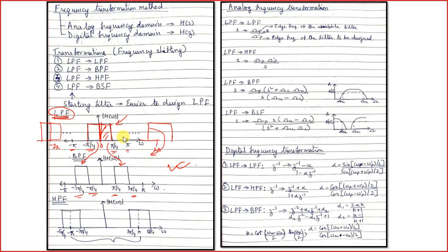Another important thing we discussed is that whatever we design in the positive half, there will be a negative impression in the negative frequency cycle also. So if I just move this part to a particular position of our need, we will be transforming the negative frequencies also in the negative domain so as to create a negative impression. Similarly, this is how we get from low pass filter to band pass filter. So it is quite easy, you can see.